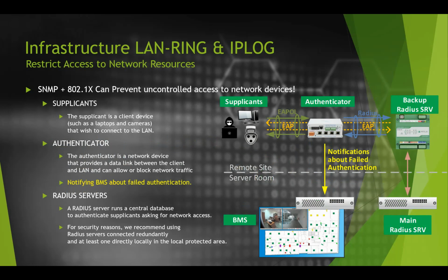Another protocol supported is IEEE 802.1x for user authentication. It has weaknesses in standard implementations. It is capable of blocking network access to unauthorized users, but that's about it. In our implementation, we have added an important feature to help you increase security. An unauthorized attempt to access the network can thus be without delay SNMP trapped to the visualization software. Thus, a potential attacker could be caught immediately and would not have time to break into the network.